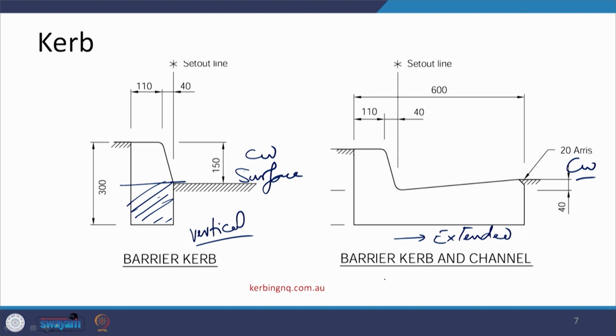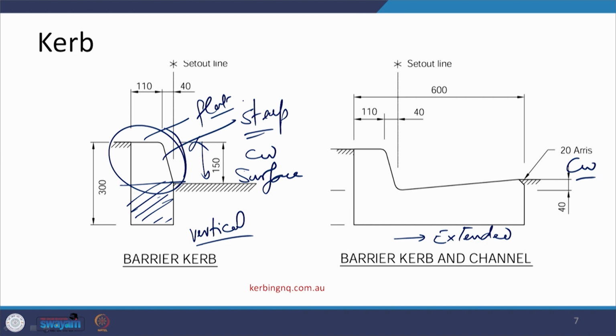Another thing which we can see is there is a certain amount of height being given here, and then there is a design, in terms of this flat surface and this steep surface. Now, these designs of steep surfaces and flat surfaces define what type of curbstone this is. Here, this particular curbstone is a barrier curbstone, which says that the vehicles moving on the carriageway will not be able to go towards the other side because of this height and design.